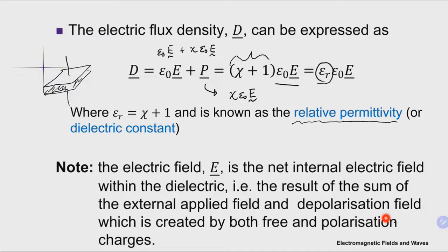For the same area, if you want to increase or decrease the capacitance, you change the material sandwiched between the parallel plates. Studied that before? No? Okay, never mind. We're going to look at that again in this module. So that is called relative permittivity.